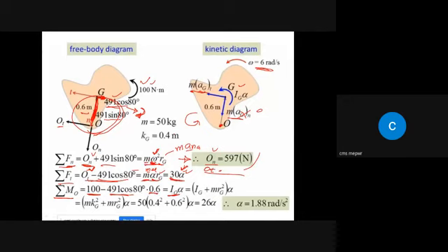And we know that I naught is equal to Ig plus m r square g, alpha, right? And we already know from the radius of gyration formula, if you go through it, we can write Ig is equal to m k g square. So I naught is equal to m k g square plus m r g square. This is basically Ig from the radius of gyration formula. Okay, that is m r g square, alpha is as it is. And on the other hand, when you put the m value, kg value, and rg value in this equation,